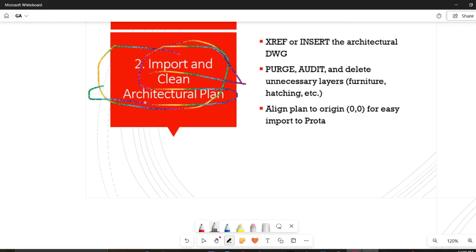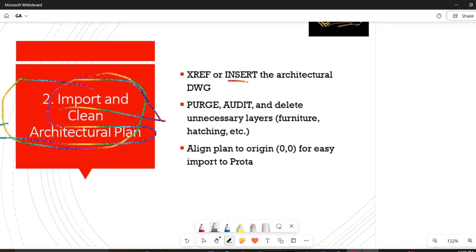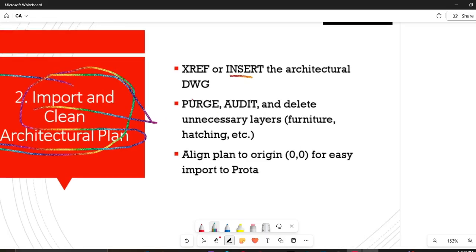Like in my case, we already had a DWG. So instead of importing, I just opened it. That is why we didn't do the insert method. We just opened that DWG and then we started creating grids and working on it. Not that much difference, but once we have the PDF, we'll have to open the model and then import, or actually, use the word insert.